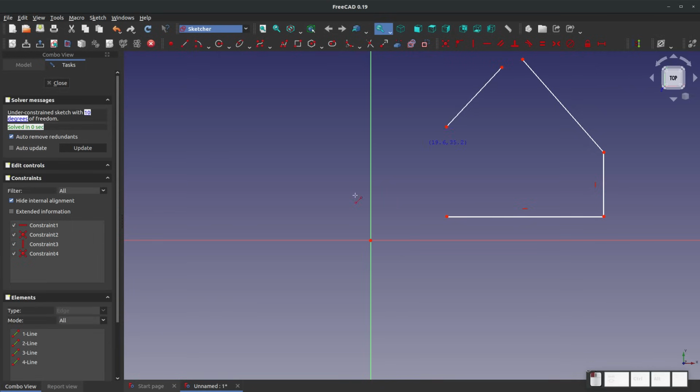So what if I draw a line and I want this point to be connected to this point? Well, you can do that initially, because when I hover my mouse over that point, it turns yellow, and I get that little red thing that shows up on the lower right part of my cursor. Those are known as constraints. In other words, if I highlight this point yellow and click to draw my line, it constrains the end of this line to always be connected to the other line. That is called a constraint, or a relation, and there's many of these that you can have in your sketch.